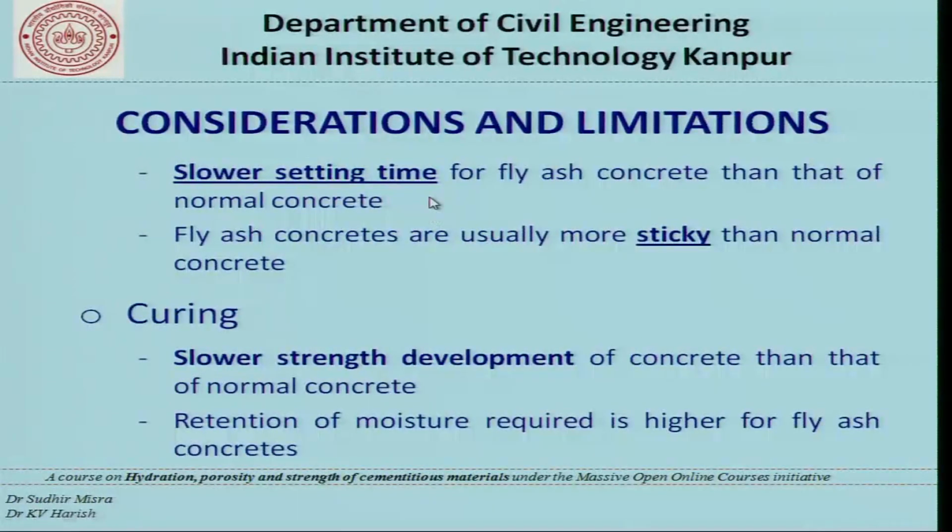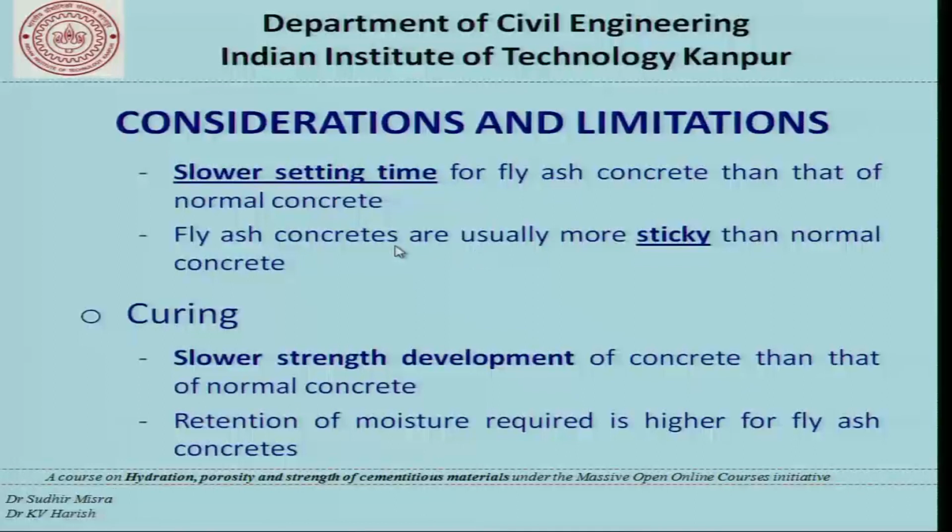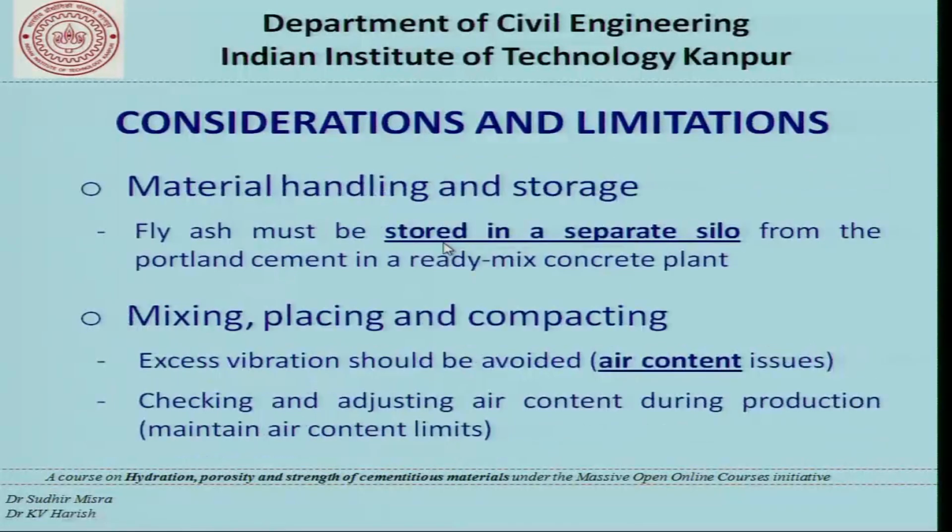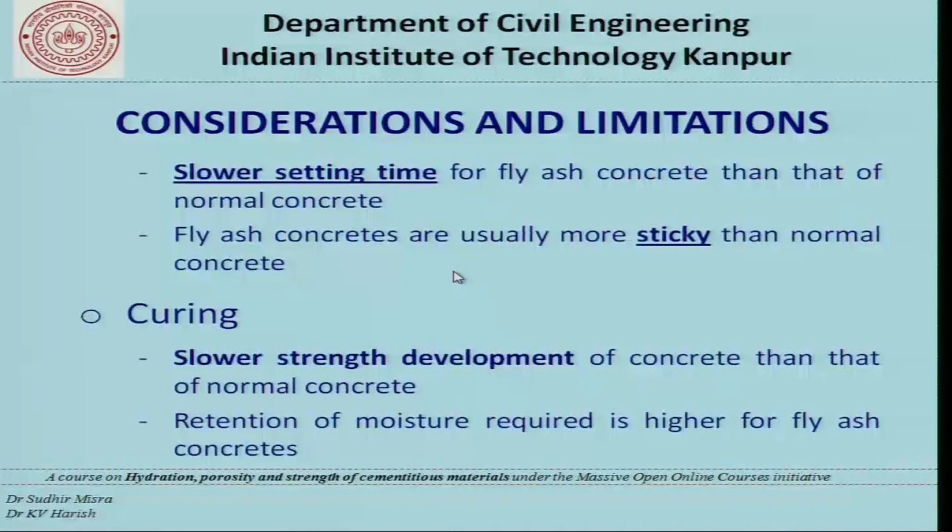In addition to that, there are other problems such as slow setting time. When you use fly ash, we have already seen that it increases the setting time. And not only that, on the other hand, it also produces a sticky mixture. So sometimes these things create problems while mixing and placing operations.